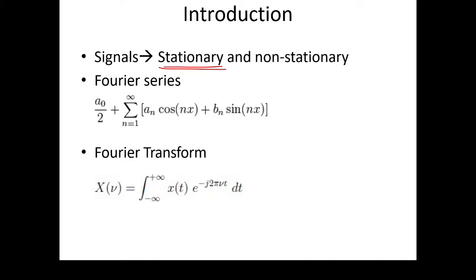The reason being, when the atrial flutter will happen, when the atrial fibrillation will happen, you don't know. You need to have the information about the time at which that frequency component is arising, and this is giving rise to a new type of analysis, the recent type of analysis which is regarded as joint time frequency analysis.